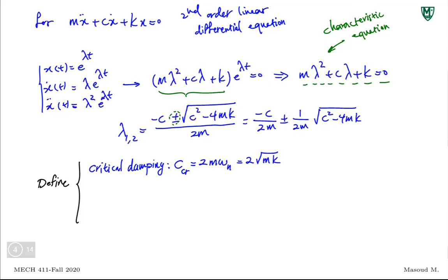And knowing that, I use it to define something else also: damping ratio. What is damping ratio? It's the ratio between the damping in the system, C, the damping constant, or sometimes damping coefficient, over critical damping. I represent that with the Greek letter zeta.